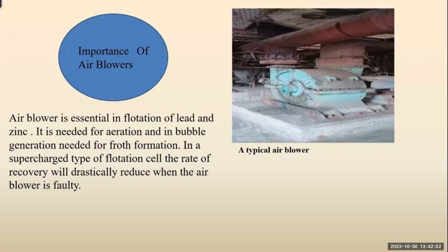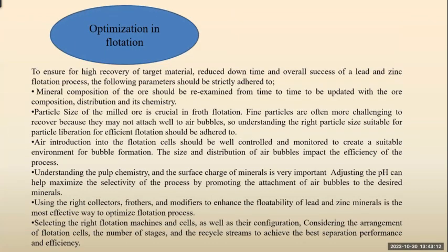So you have different kinds of rotors and stators, because in some designs, at the entrance of the cell, that is where the feed enters the cell, you have a head agitator that goes with a propeller, which is different from the rest, because that one now has to create a vacuum to be able to suck in, because your flow is going through using gravity. So that head sucks materials in.